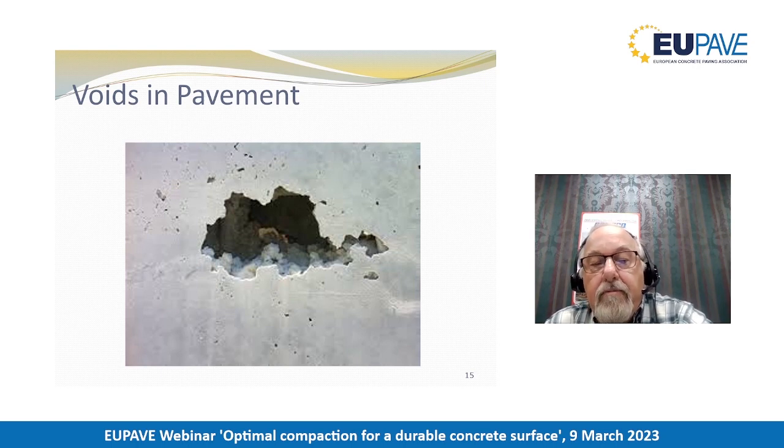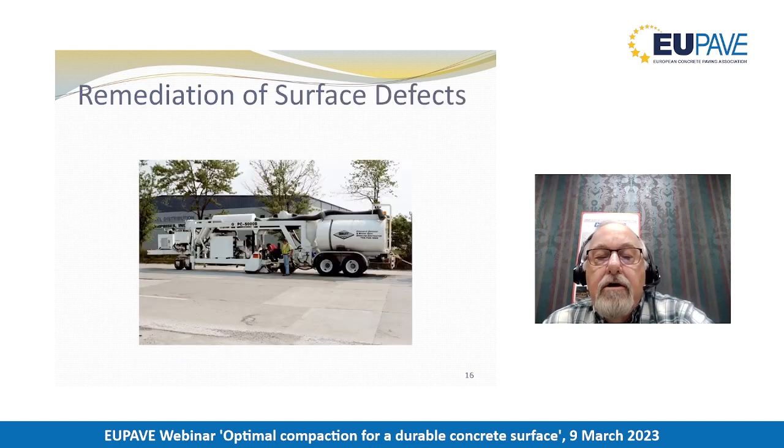But the first thing I'm going to do if I see that is I'm going to go back and re-engineer the mix. And the second thing is I'm going to look at the machine setup and the amount of vibration energy required. So this is our go-to when we have surface deterioration. We simply grind the surface. Well, grinding the surface by itself most of the time is going to be sufficient, but there are many cases where that is not the case.